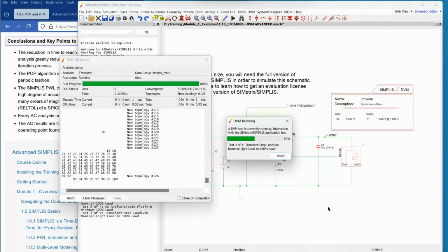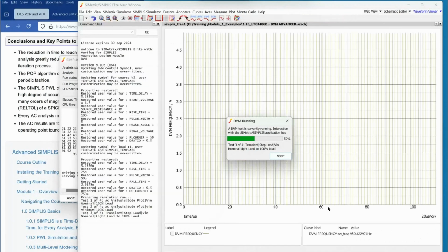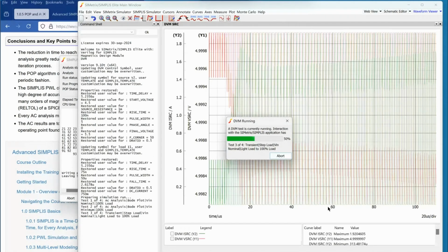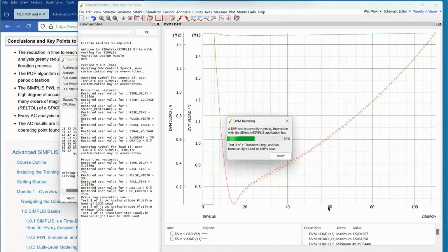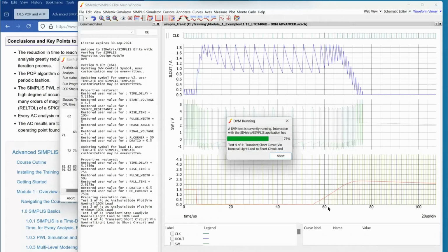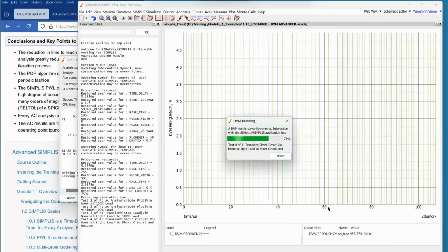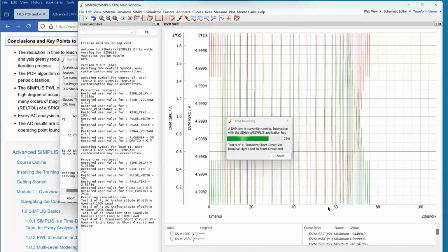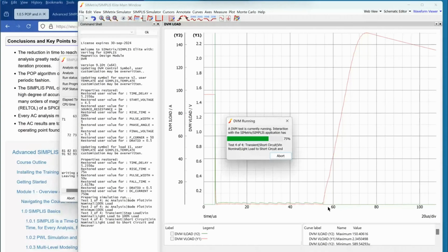And then it will compare those measurements to the specifications, if you have specs for those measurements. And you have different specs for each test. Once you've run all the simulations, gathered up and measured the waveforms, and compared them against the specifications, it'll automatically generate a test report for you.